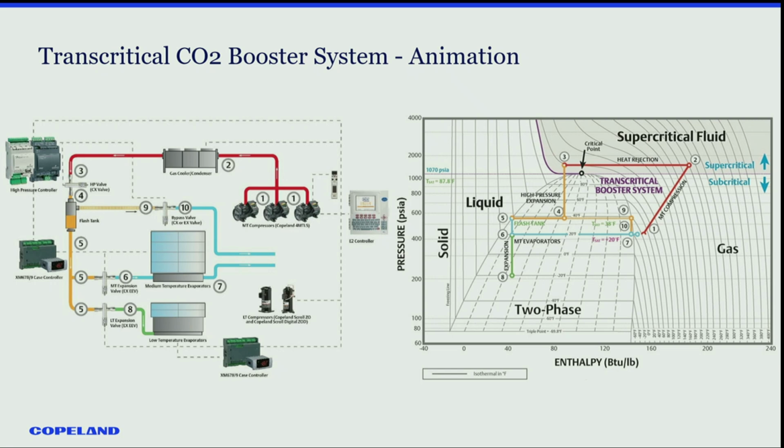As you get a situation like this, you've got a greater percentage of flash gas. That means you've got to open this valve even wider, and you're sending more mass flow into the medium temp, you're paying more taxes. That means you've got more compressors that have to run just to manage this bypass gas flow that does how much refrigeration? Zero refrigeration, right? So on the hottest summer day, you might have 45% of these compressors running just to manage that bypass gas. And that's a tax. You're paying energy to have those compressors run. So that's kind of a different way of looking at it. And of course, the medium temp compressors have to handle the total heat of rejection of my low temp, all my medium temp mass flow, plus this bypass mass flow that could be close to 50% on the hottest summer day. So that's the way I like to kind of walk through this chart.